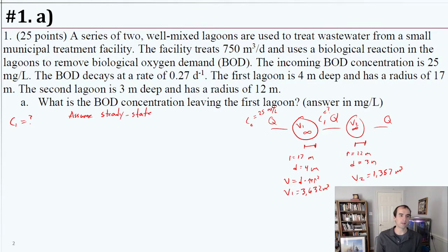Well, that shows me at least that, once you've made that assumption, if you then follow the process for a steady state system, that at least shows me you're aware of what that steady state means, even if you missed part of the concept that something changed in the system which indicated it was no longer steady state. But there's nothing like that here. So this would be steady state. That means our accumulation term goes to 0. And so the net accumulation in that first reactor will be no accumulation. We'll do a mass balance on that first reactor here.